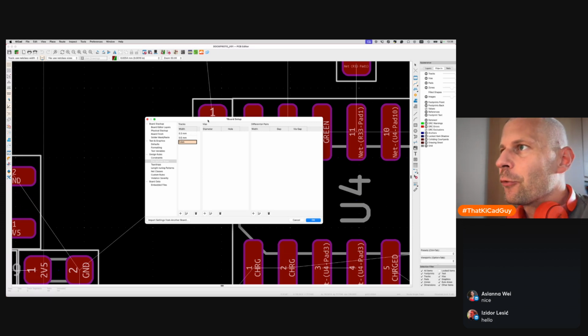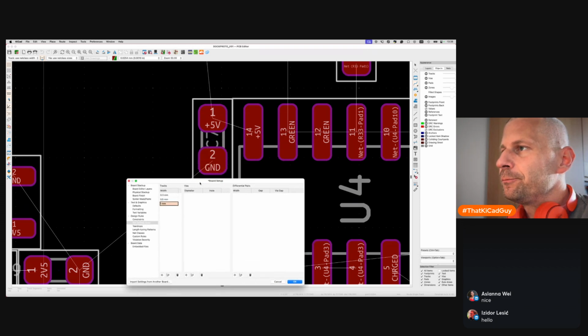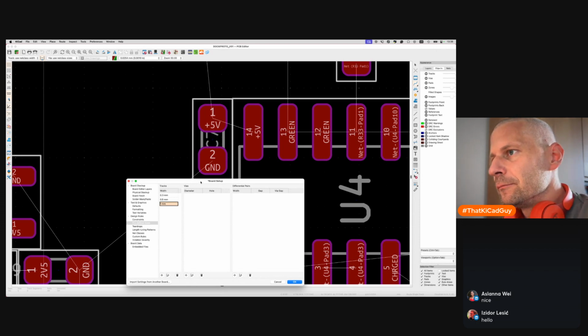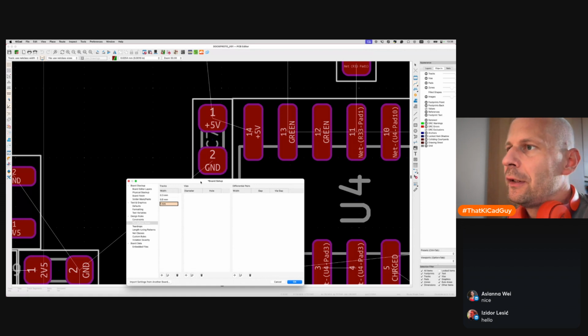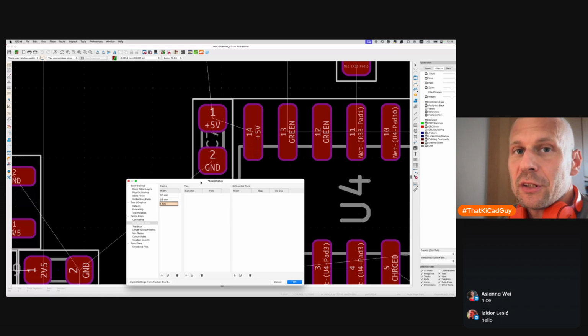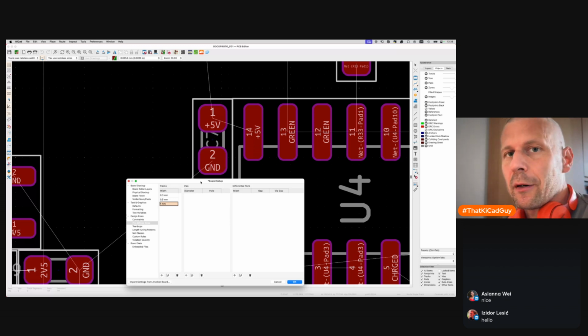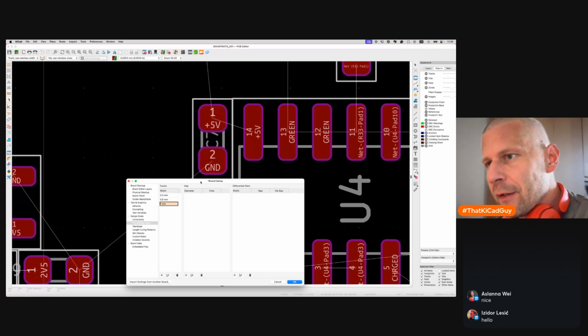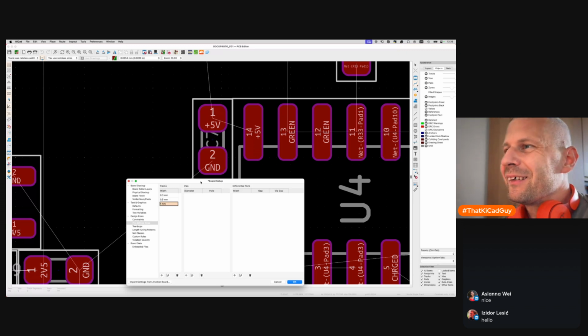It's quite comfortable to work with. The PCB layout is still neat and tidy, and I don't want to use the minimal thicknesses because the PCB manufacturing is then challenging. The machines at the PCB manufacturer's shop are able to create even tinier tracks, but I like to have some headroom.